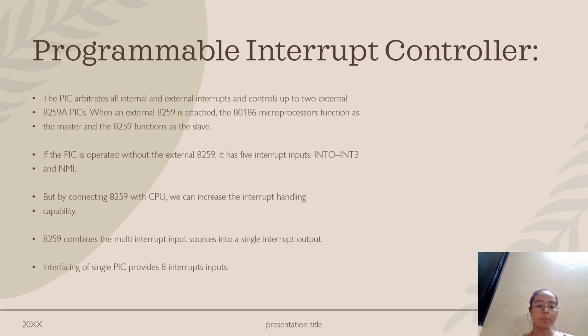Interfacing of a single PIC provides 8 interrupt inputs. So simply, without an attached 8259, we cannot handle all the interrupts that occur in the microprocessor, but with an attached 8259, we can handle all the interrupts.